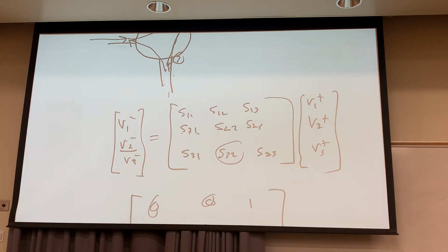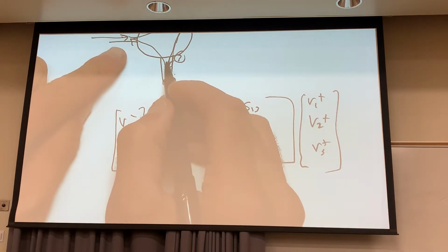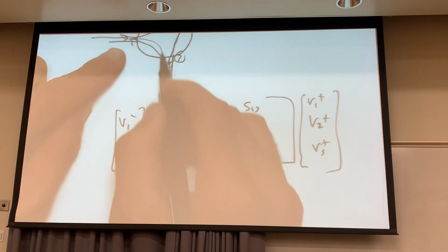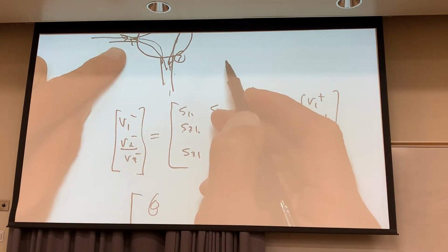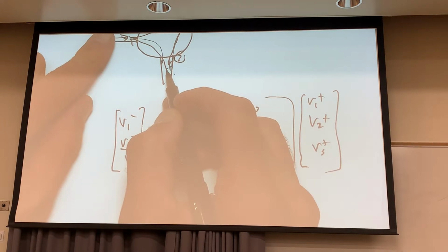The signal comes in port 1, you want less than 1 millionth, or probably less than 10 million or 100 million of that signal strength to come over here, of the power. So what they try to do is make sure that some of this signal can't go back in. It'll destroy the amplifier if you're not careful. And they probably have additional switching that literally takes this port offline when they're transmitting this signal. It's very fast, because that can destroy it, but they still have circulators.